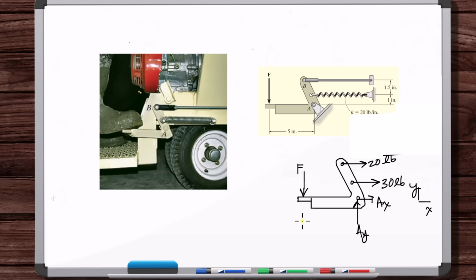Remember, the assumptions are problem specific. If the loads I input here, the known loads, are big enough, this is not going to be a rigid body. This will spread out and deform. So if the loads that I introduce into the problem are big, this piece of steel might not act as a rigid body.